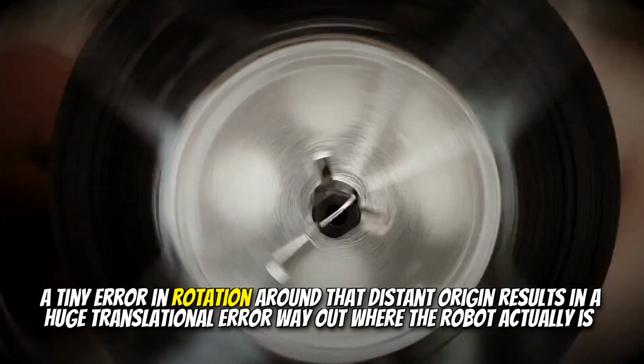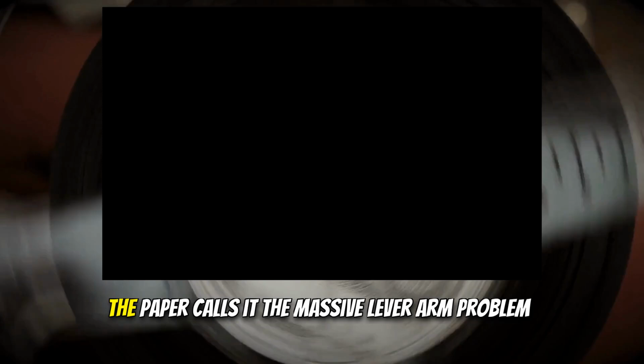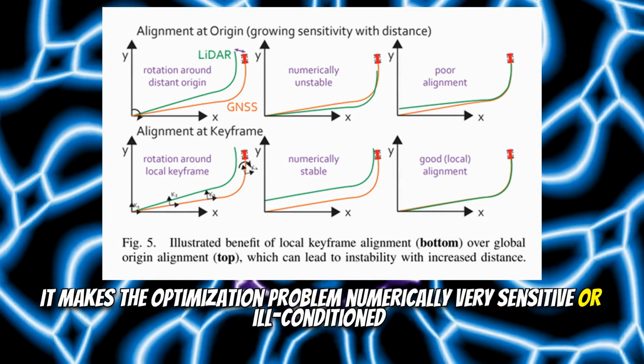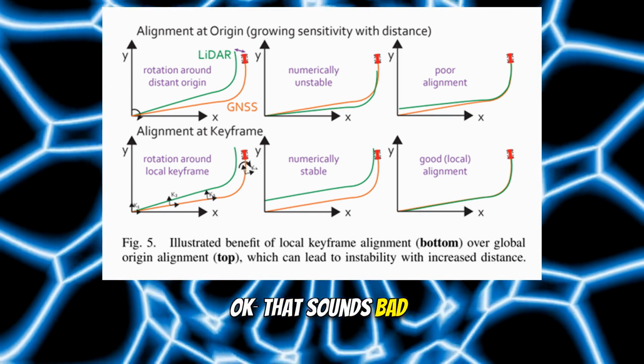A tiny error in rotation around that distant origin results in a huge translational error way out where the robot actually is. The paper calls it the massive lever arm problem. It makes the optimization problem numerically very sensitive, or ill-conditioned. Small measurement noises can lead to huge jumps in the estimated state. Okay, that sounds bad. How did they fix that?